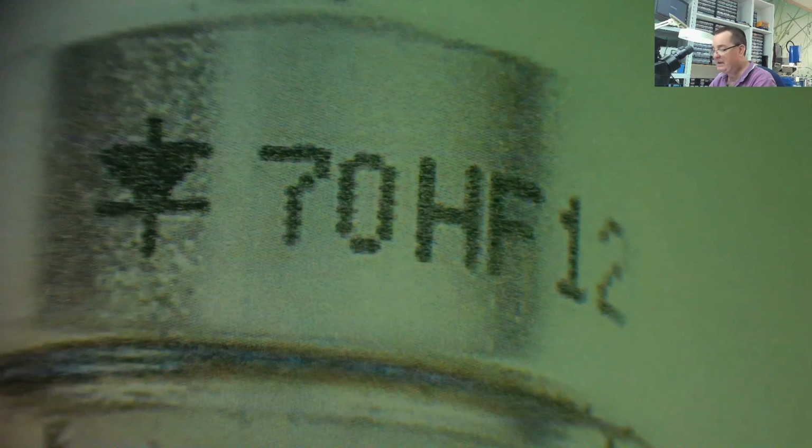I don't physically have one of these to show you, but I can show you a picture of one. So this is a high power diode. It's actually a 70HF120. It's a 70 amp, 1200 volt, high voltage, high power rectifier. And this has a big metal stud on it, and the bolt. These are called stud diodes, so it comes with the washer and the stud and the bolt.